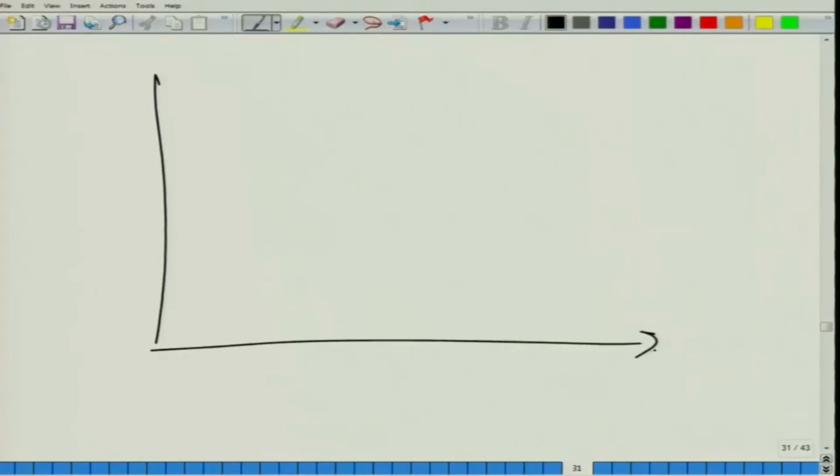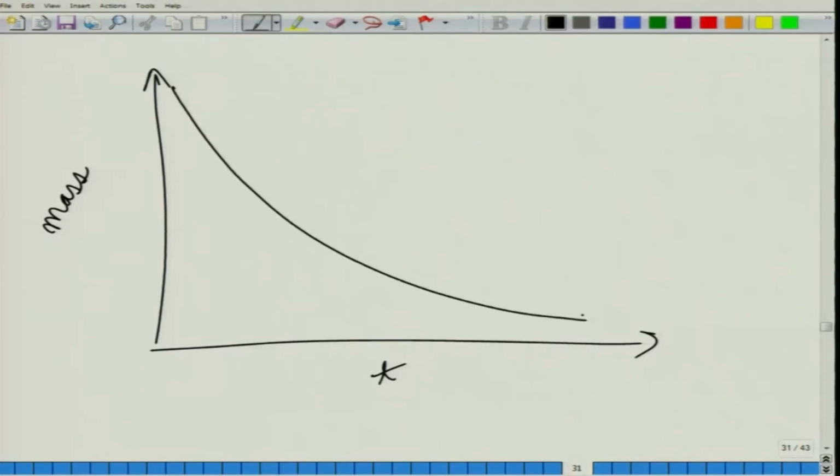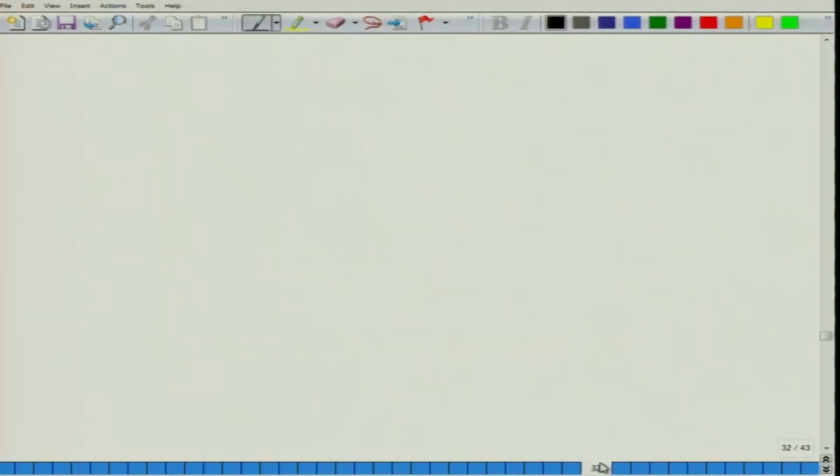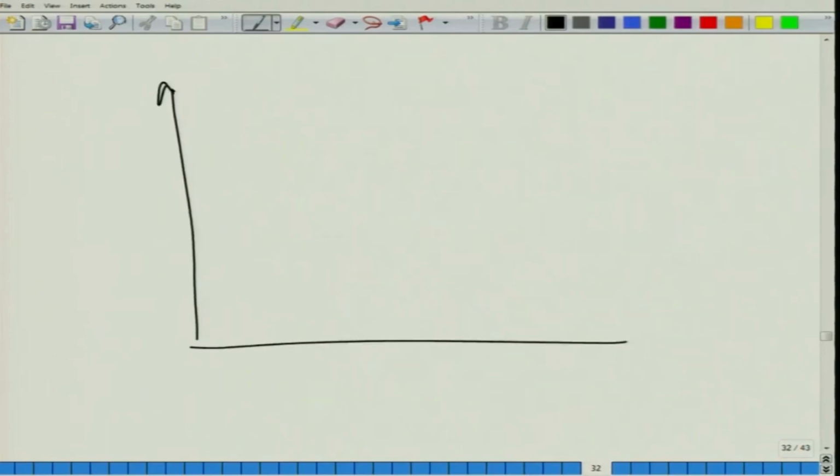As we saw in a previous curve, when we plot the mass of your sample versus time t when you are putting it for drying, the mass reduces with time, but when you put your sample inside water and plot mass versus time, your sample is going to absorb water till it becomes fully saturated with water. So, when you put your sample inside water, you should take your measurements as soon as possible, or otherwise your sample itself is changing with time.